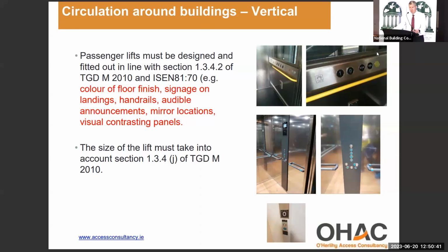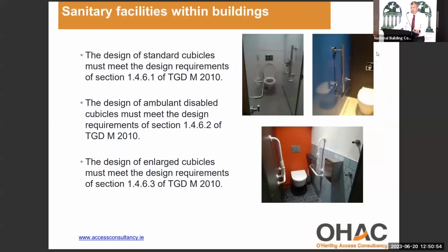Also, to be aware that the size of the lift for certain types of buildings is 2 meters by 1.4. So that's for particular places like theatres and libraries. So just keep an eye on that one, the design of lifts.